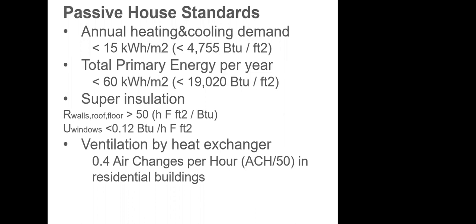We know what triple glazing is. Argon filled means that for the cavity between two glass panes, air is not enough. We need to fill it with argon. Argon is an inert gas. And low emissivity is a coating. It's something invisible, so we don't see it, but it performs really well in terms of energy savings. Okay, so that's it.